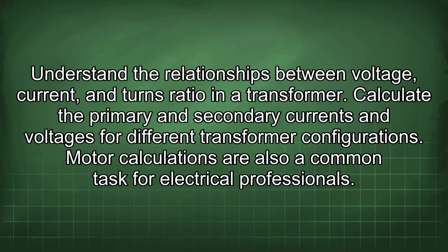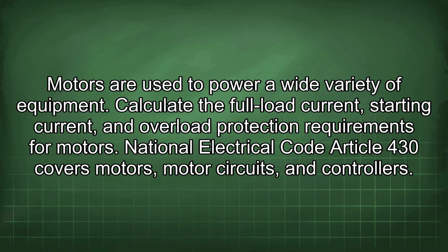Motor calculations are also a common task for electrical professionals. Motors are used to power a wide variety of equipment. Calculate the full load current, starting current, and overload protection requirements for motors. National Electrical Code Article 430 covers motors, motor circuits, and controllers.